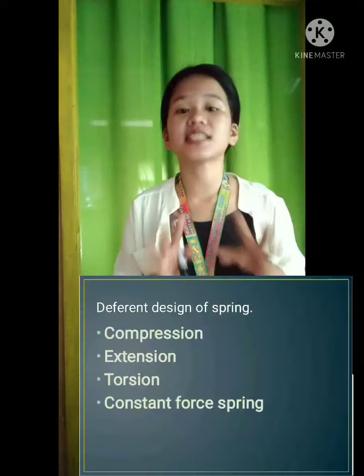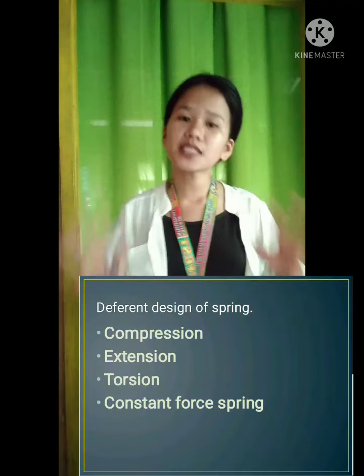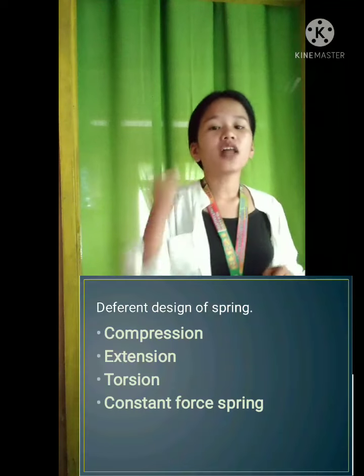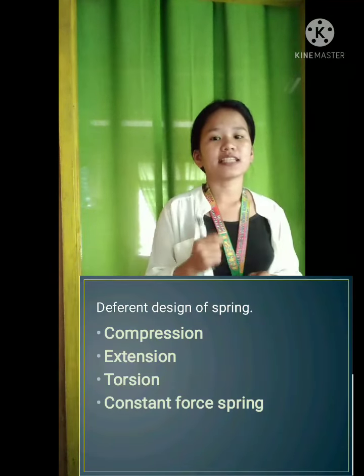The minimal value of the stress which produces plastic deformation is known as the elastic limit for the material. Any spring should be designed and specified such that it only ever experiences elastic deformation when built into a machine under normal operation.